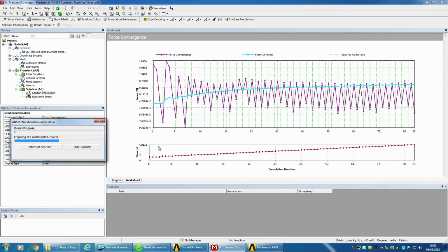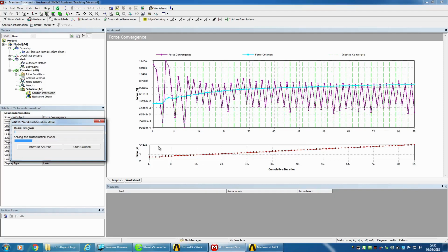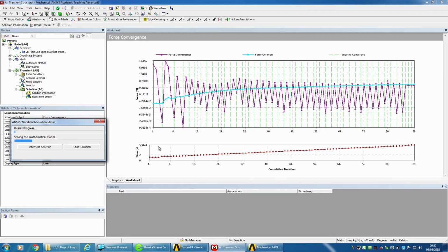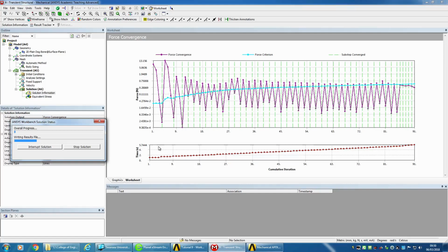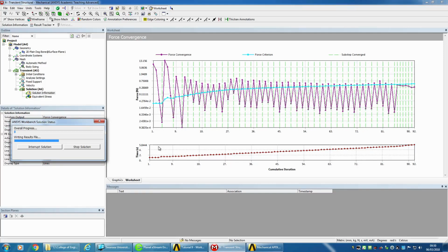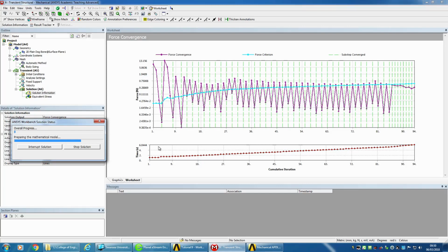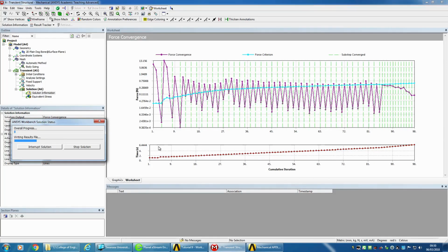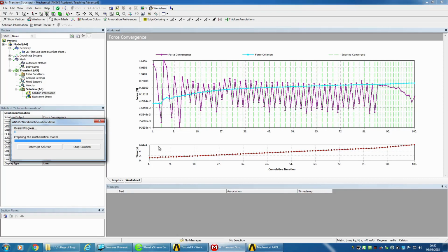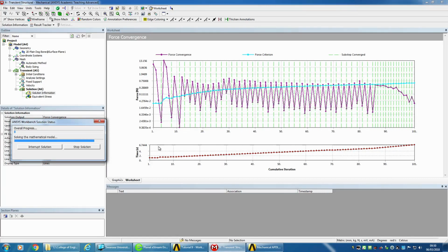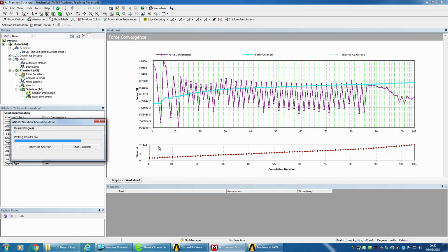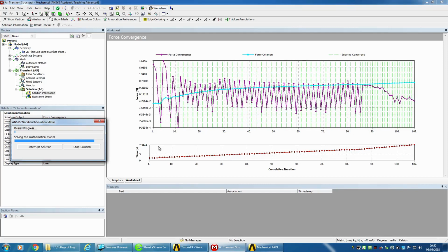I can't remember exactly where, but I think around about 120 seconds this thing will finally die, and that's one of the rather unelegant things that happens in ANSYS. You can solve a linear elastic problem, and you will rarely get any problem, and it will keep on converging, and you'll keep on getting the most ridiculous answers in the world. You get this massive deformation post where your yield stress would normally be.